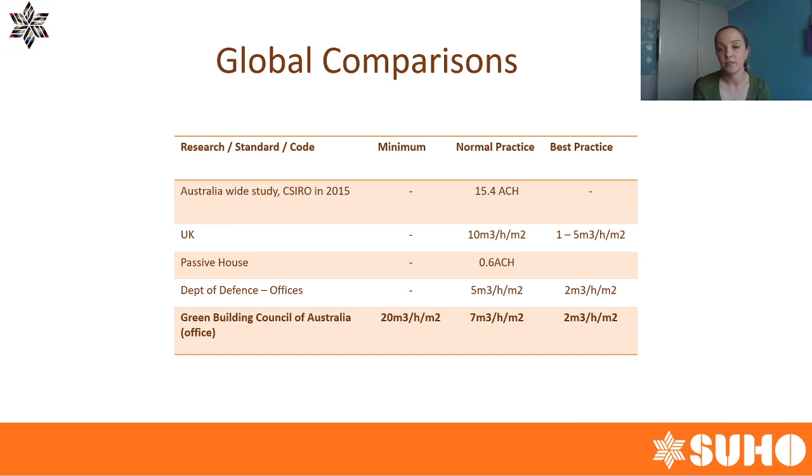And I, for one, just like knowing the data side of it, it's very interesting to me. So if you're the same, if you're a builder and you want to know where your current building stock is at, it's a really useful thing to just get a blower door test done and benchmark yourself. We've had a few builders do that and they find it very valuable. The first time I saw a house under negative pressure and used my thermal camera, I was fascinated at all the leaks that we found that I had no idea existed before. So it is a really valuable exercise.